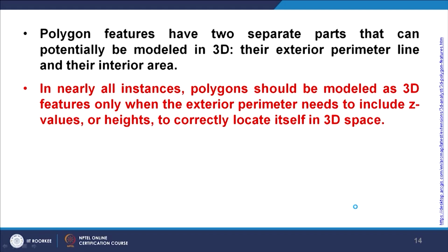So, along with polygons also, if a plot or an agricultural land has undulations, then against that plot only one single Z value will be stored, and you know in the real world there are undulations. So, if you want to store undulations, you have to have separate polygons, or there is another way of representing such things: go and resort to raster data rather than vector or polygon data.